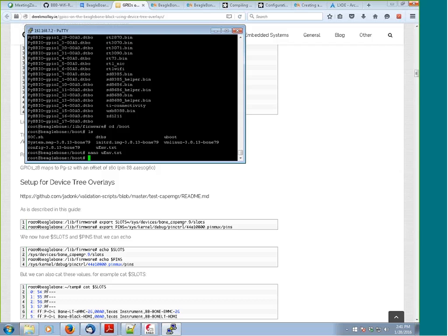So at this point, I went back to the BeagleBoard groups. I looked around, and I found in a frequently asked questions a very specific note about this. And what it was is that the uEnv text in the latest Debian image runs once, but it doesn't keep trying to get the cape to load up. Because remember, when Linux is booting up, there's a lot of things happening in a certain order. And sometimes if the cape doesn't try to load at the right time, it'll fail. But if it would have run later on, it would have worked. So the workaround for this for the meantime is actually to adjust another file.